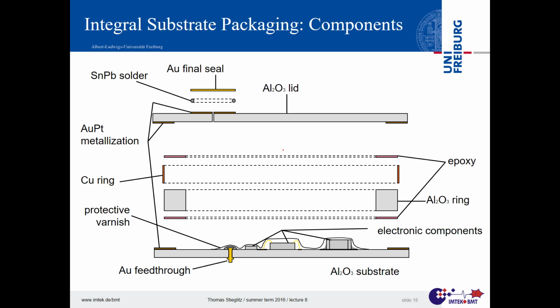If you do a packaging with silicone rubber, it has a very, very slow diffusion rate for anything else but water vapor. Very little with respect to ions, and very, very little with respect to heavy metal ions. That means if you do that well, you have no leakage of lead into the body.